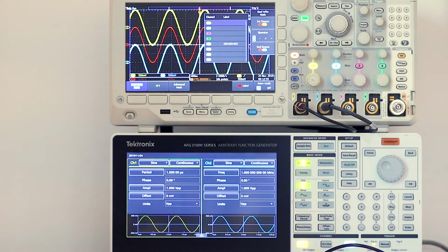Any two waveforms can be added, even if they are totally different types. They are added on a point-by-point instantaneous basis. Notice here that when the peaks of both go high, their sum goes high, and when the peaks go low in a negative direction, the sums in red go twice as low in a negative direction. When the sources go to 0, as when they cross the x-axis, as at the left edge of the display, the sum is 0.